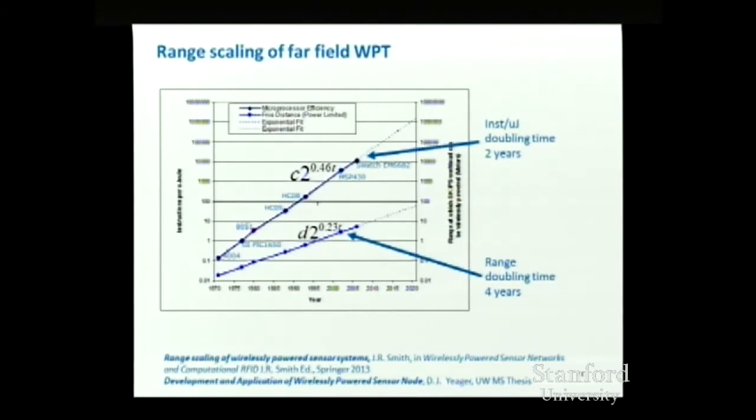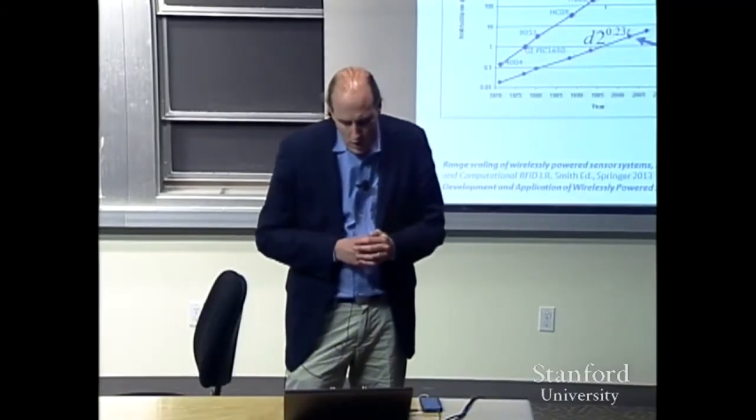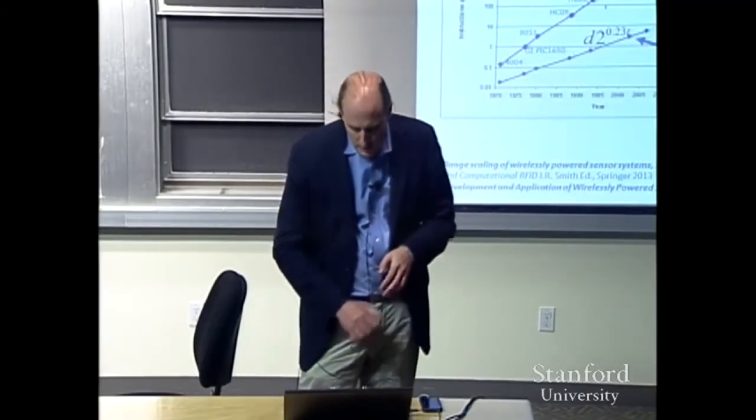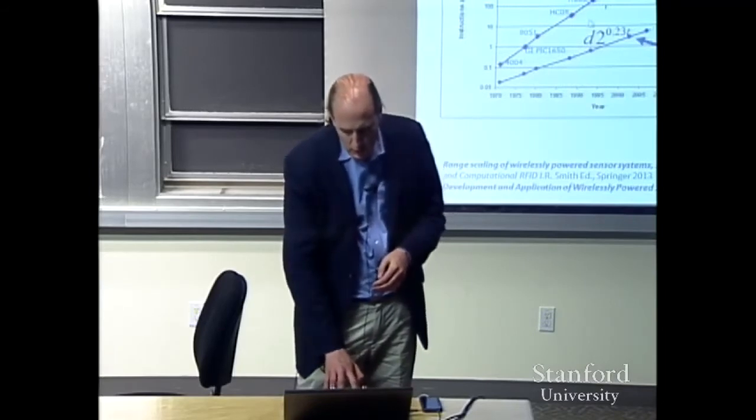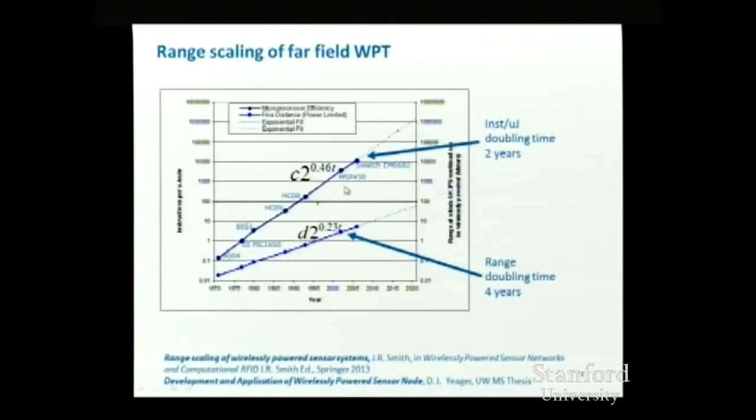And we assume we can transmit a certain amount of power wirelessly. So, the law allows us to transmit a certain amount. That power falls off as 1 over r squared with distance. So what that means is that if I pick a particular workload and I assume that I'm going to be able to execute it on increasingly efficient hardware, that means the range at which I'll be able to execute that workload is going up exponentially too.